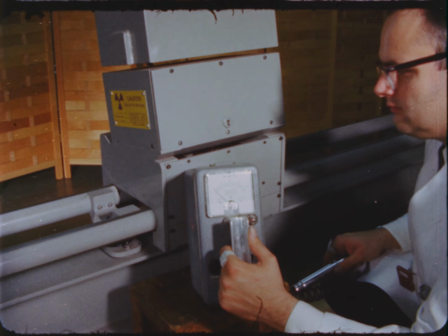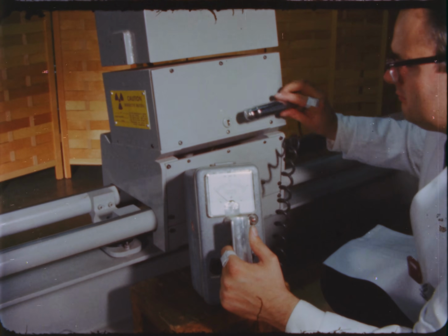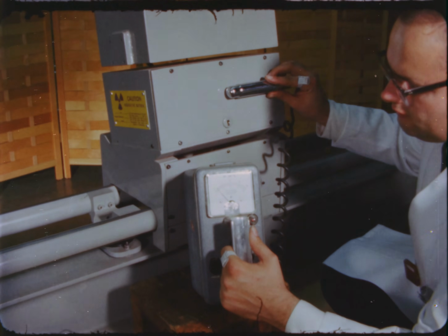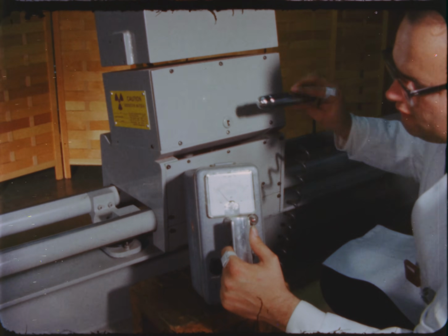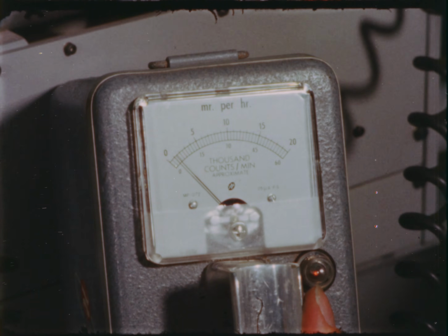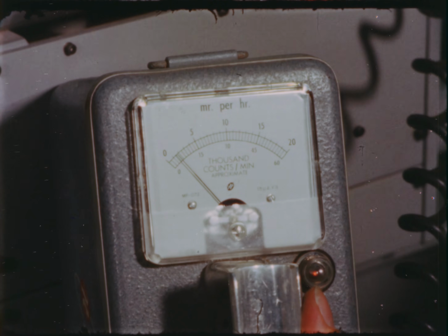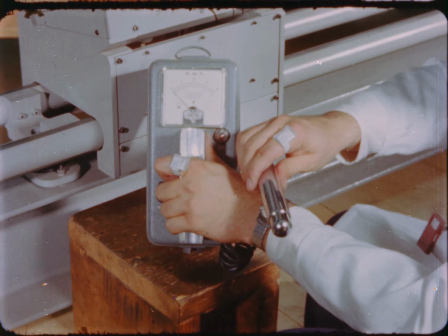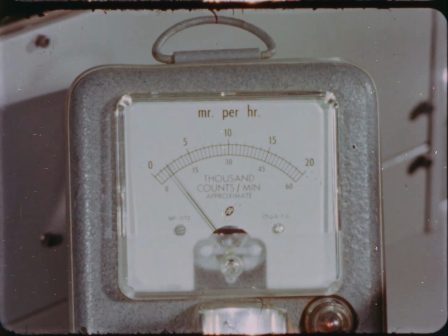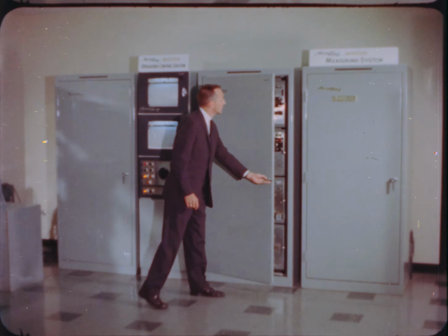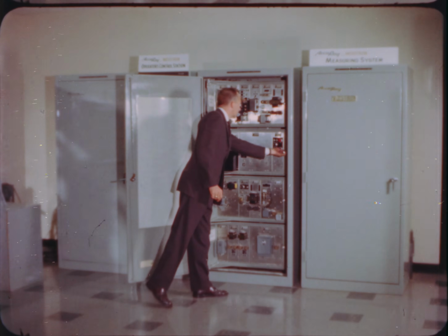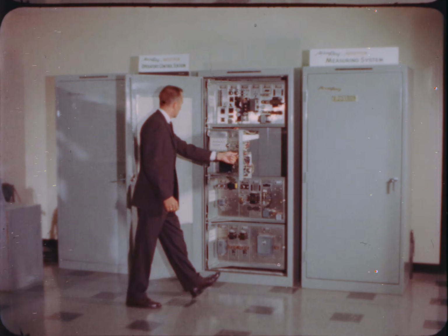In industrial use, the level of radiation necessary to do a particular job is usually comparatively low. Take, for example, this gauge used to measure the thickness of paper. The beta radiation emitted by the radioisotopic source is so low that it can be compared with the radiation given off by the luminous dial of a wristwatch. Adequate protection from low radiation levels is assured by the design and construction of equipment housing the sources.